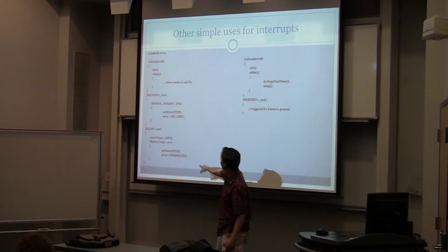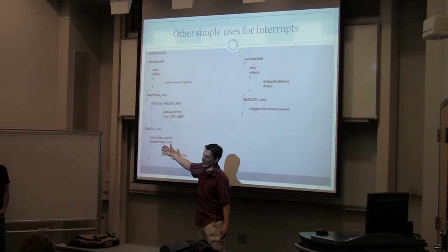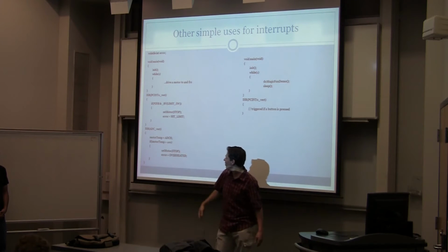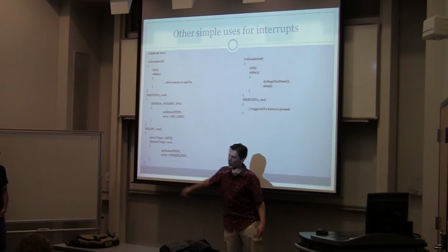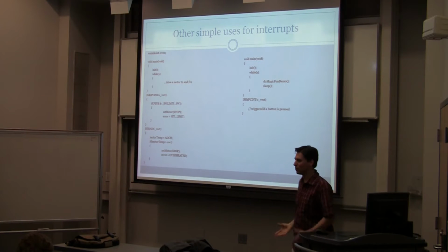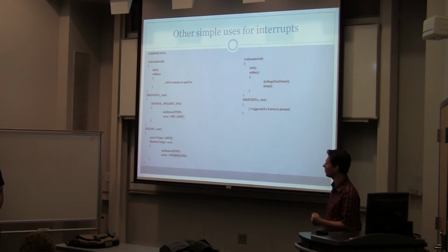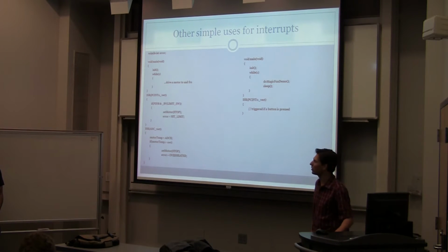And then also, you can check the motor temperature. Maybe you've got a motor with a temperature probe on it. If it's greater than a certain value, turn off your motor right away. So usually with microcontrollers, there are certain things, especially when you get bigger embedded systems, that you want to do right away. That's one case where interrupts are good.